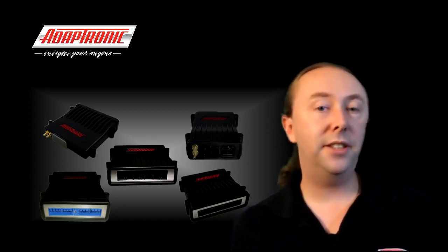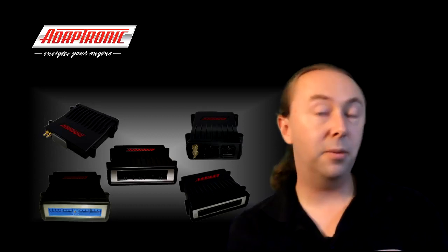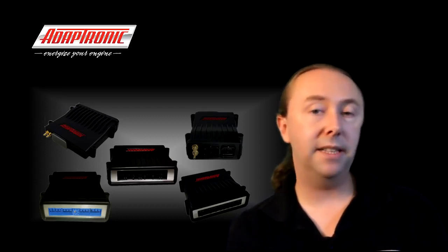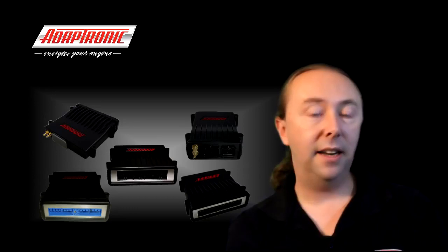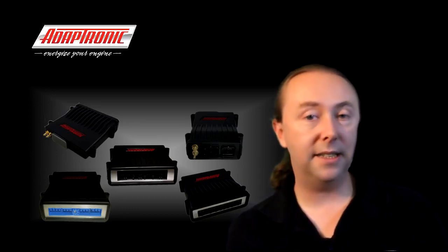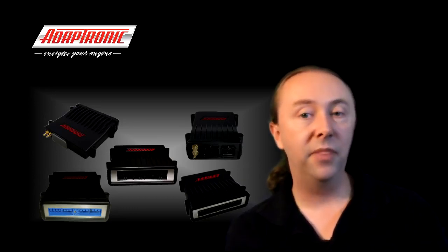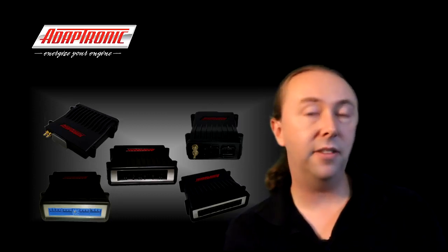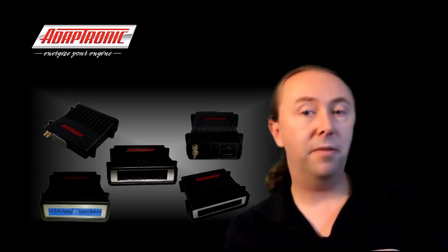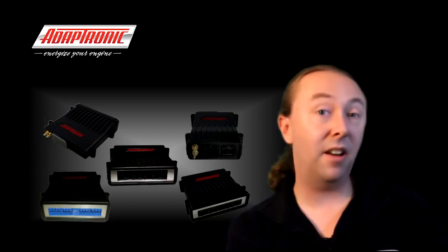Now also, for every injector at any given fuel pressure, there's a minimum voltage that needs to be applied to the injector for it to be able to open. Now we find in testing some injectors that some of them won't open at 5 bar pressure at a low voltage, like say 7 or 8 volt. I've even seen some injectors that won't open reliably at 4 bar pressure with 9 volts.